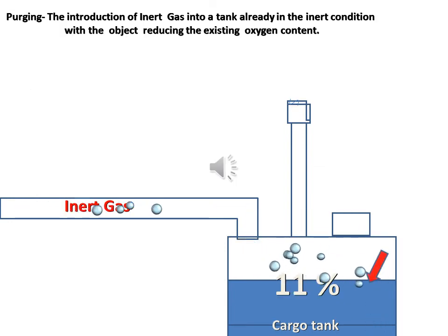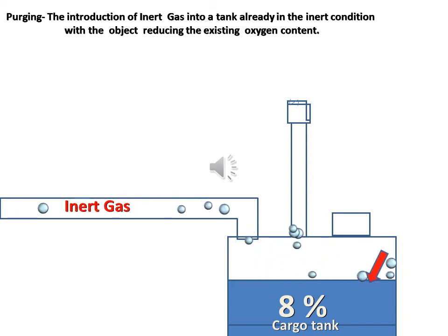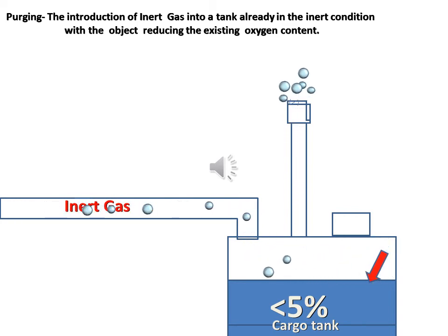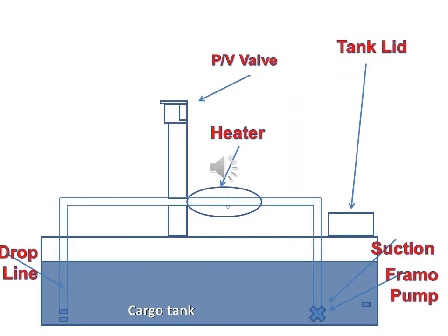Gas system inerting must be carried out during loading, on voyage, during unloading, tank cleaning and for purging prior to gas freeing. This is also a procedure for blending the cargo or when you are circulating the cargo through a heat exchanger.